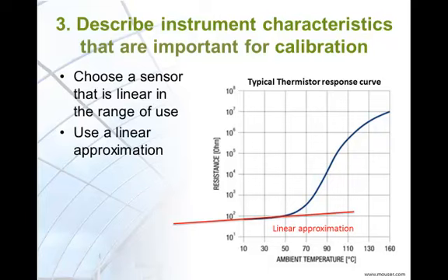In this particular case, if the temperature rose much above 50 degrees Celsius, the temperature sensor would be inaccurate using this linear approximation. However, we do not expect to see temperatures above 50 degrees Celsius in a greenhouse where temperature is being monitored and controlled. Working with linear functions makes working with the sensor less complicated.